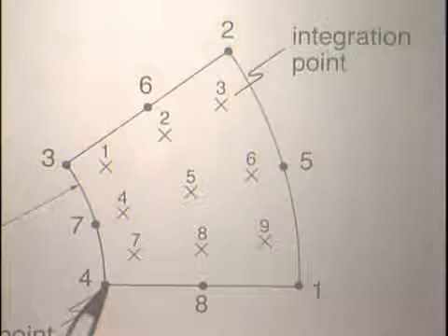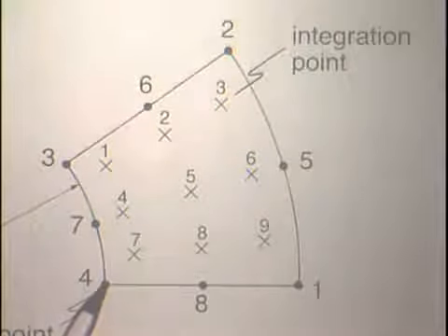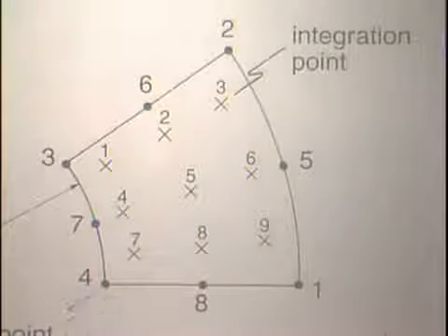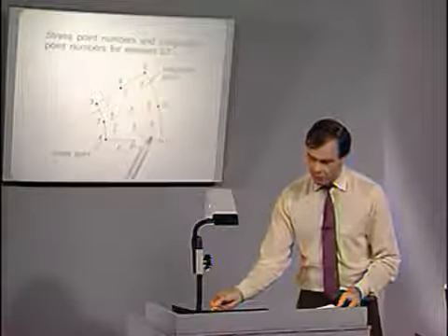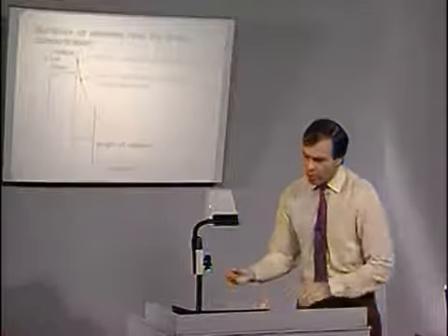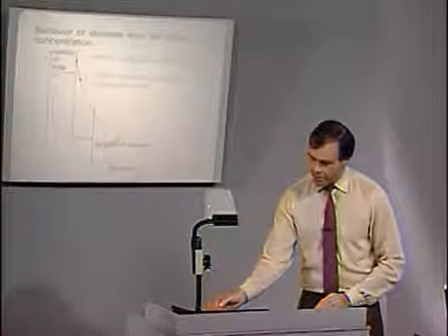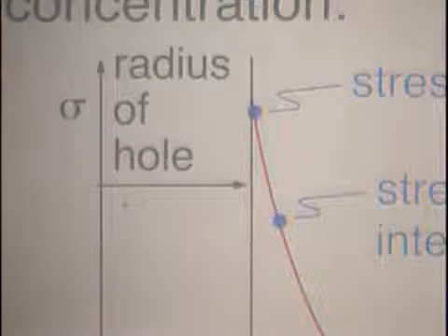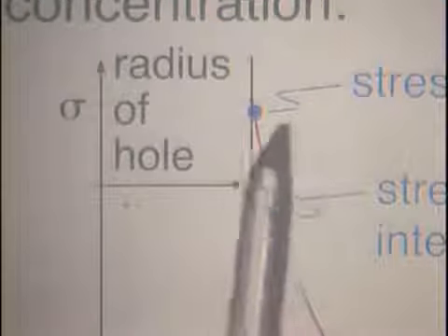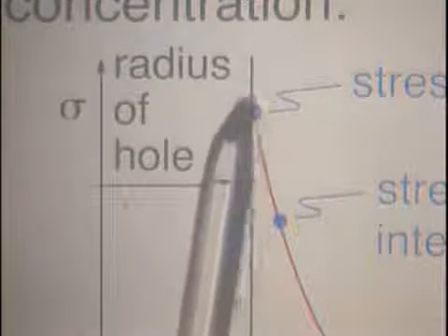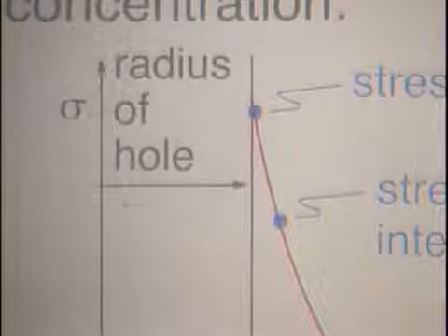Of particular interest is also this point here, where we anticipate to obtain the maximum stress in the analysis. If we look schematically at how the stresses would vary through the element to the boundary of the hole, we would see a schematic plot as shown here. Here is an actual element, the other elements lie next to it, and here you can see schematically the stress computed at the closest integration point to the boundary of the hole, and here we would have the stress computed at the nodal point. That is actually the stress that we are interested in.